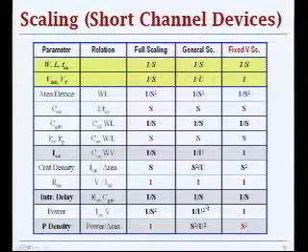What this also tells you is that the power density, which is clearly the problem, is somewhere in between the full scaling, which is the ideal scaling scenario, and the fixed voltage scaling. This is the model that you really need to understand. That's the important model underlying the development of modern technologies. Any questions about scaling?